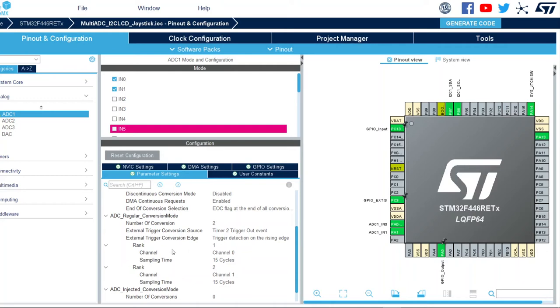Normally this doesn't greatly affect how fast it would reconvert. It's just that the microcontroller wants an instruction as to which ADC channel to convert first. So I just enter channel 0 as first priority or first rank, and select channel 0.